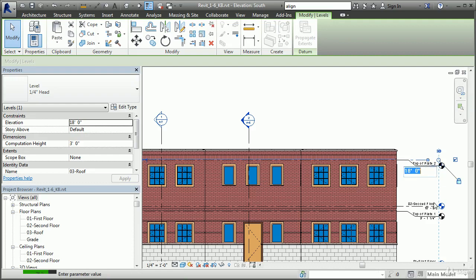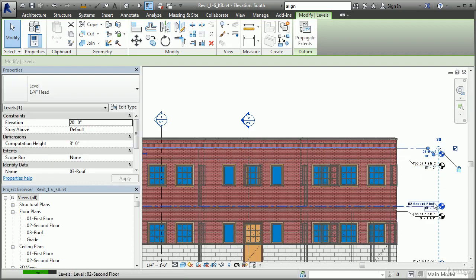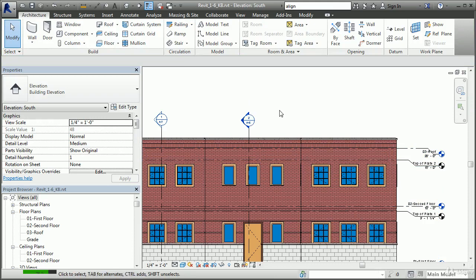So just by changing a single value here, we can adjust the entire shape and size of the building. In a regular CAD drawing, changing the position of an element, such as a window, by stretching it, will also update any associated dimensions. In Revit, this is also true, but it's taken a step further, as you can actually select any dimensioned element, such as a door or a wall, and its dimension values will be highlighted. Modifying that dimension value will actually modify the position or size of the dimensioned element.